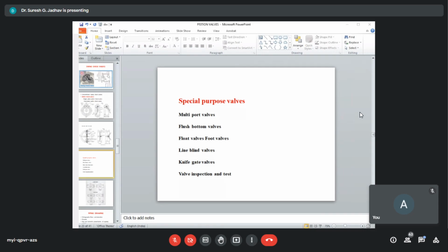Check valves shall have pressure applied to the upstream side. When valves with a stuffing box are tested, the back seat shall be tested for leakage with the valve in the fully open position and the stem packing removed or untightened.